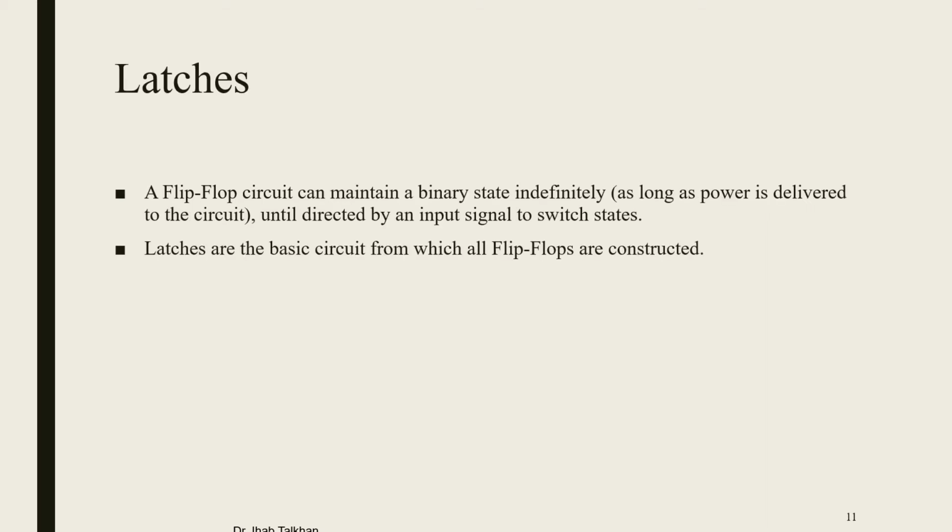Let me start here with the latches, which I discussed with you in the videos I uploaded in the Google Classroom. Actually, a flip-flop can maintain a binary state indefinitely as long as power is delivered to the circuit, until directed by an input signal to switch state. So whenever you have a value inside the flip-flop, as long as there is no clock, it will keep the value inside it until it changes. If you want to change it, you put another input, and the clock will accept that and change the value of that flip-flop.